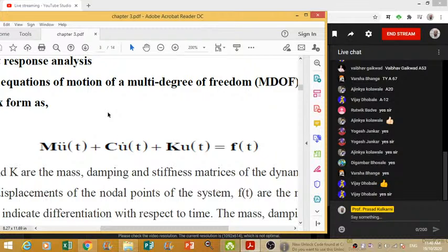See, most of the students have confusion in their mind. Sir, I want to do the vibration analysis. So this word, vibration analysis, does not exist in ANSYS software. There is a transient analysis, there is a dynamic analysis, explicit dynamic analysis. So types of analysis are defined and the output of that analysis will be a graph of the vibration. So if you want to do the vibration analysis, you can go for the transient response analysis. What you will get in the transient response analysis, we will see ahead.